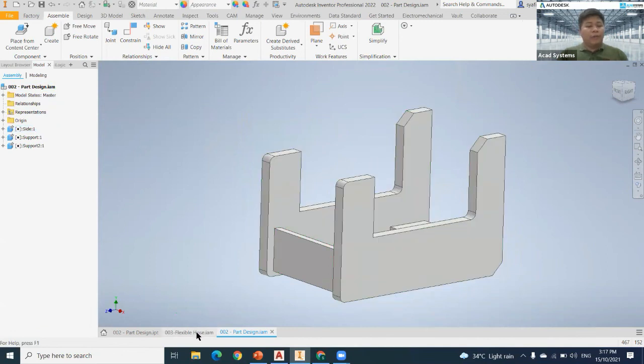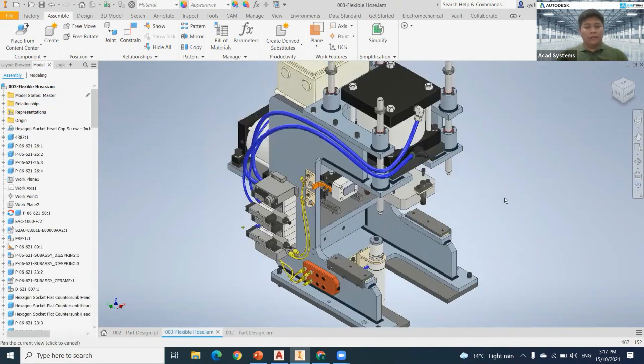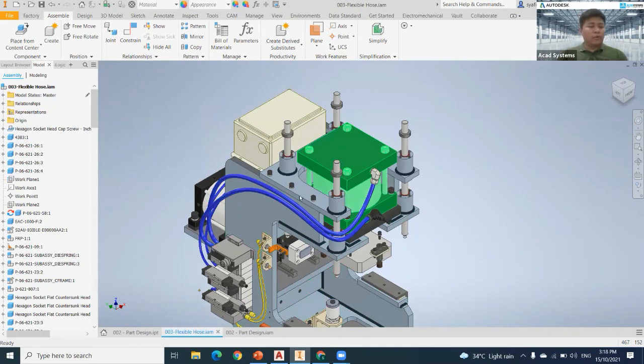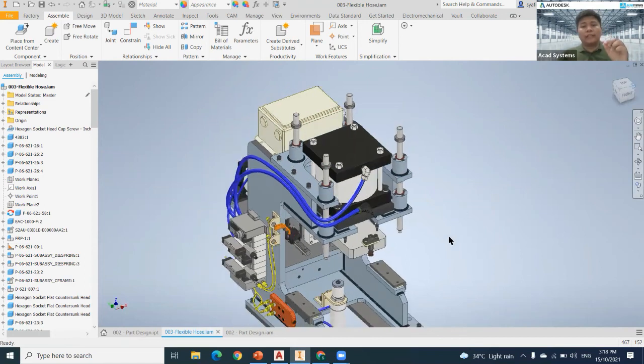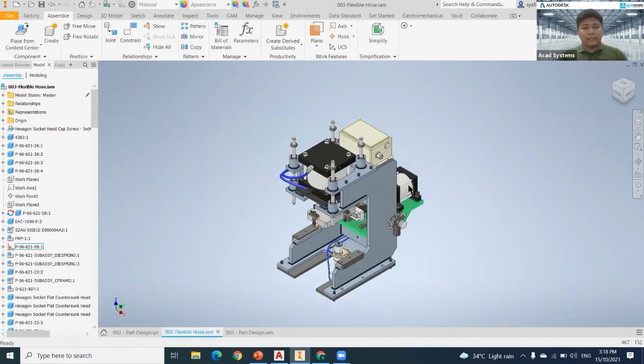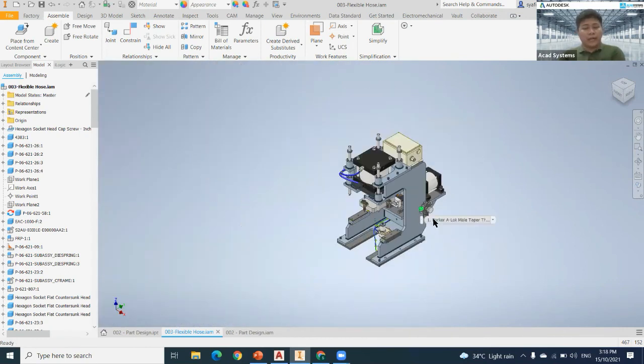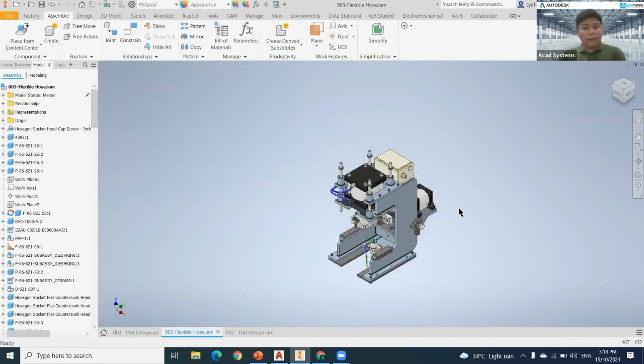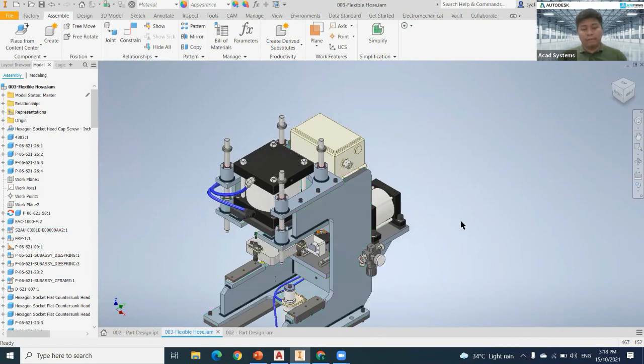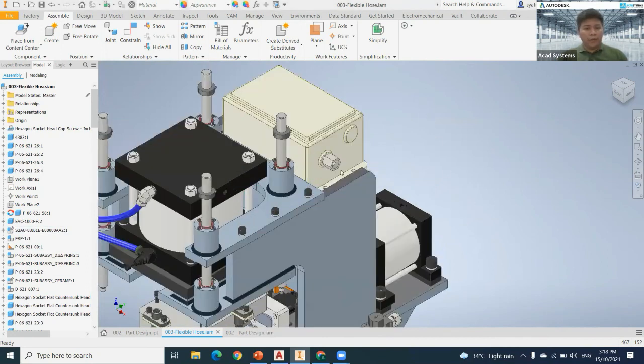I believe you also have all types of files, including the motor or any 3D CAD from your supplier, which you are able to insert into your assembly. Over here, I just want to add some interesting topics. When I'm already done with my machines and I want to create a tube or piping for my 3D model, the normal method people use is a sweep.